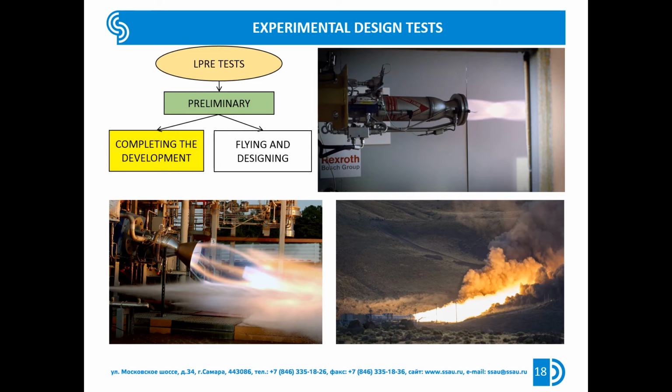At the final stage of final development tests, when the confirmed reliability level of the developed LPRE is sufficiently high, bench tests of the LPRE as part of the propulsion system are conducted. The main purpose of these tests is to provide a preliminary assessment of the performance of the liquid propellant rocket engine as part of the propulsion system. At the same time, the effects of the liquid propellant rocket engine on the propulsion system performance are examined. If several liquid propellant rocket engines are installed in the rocket stage, their mutual influence and their impact on the performance of the stage are assessed.